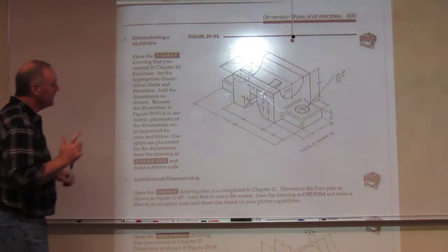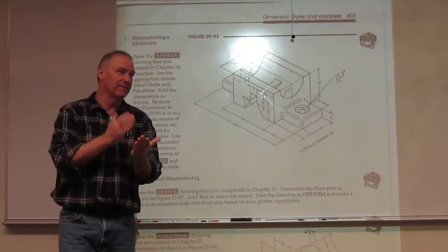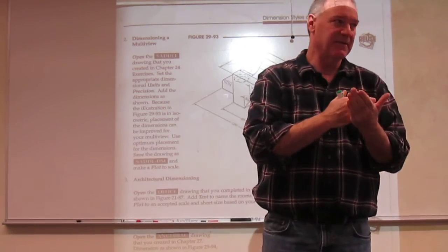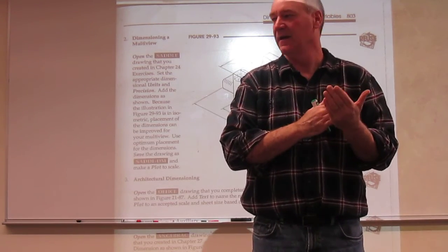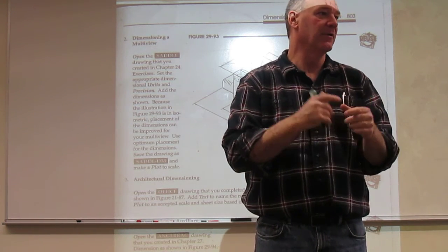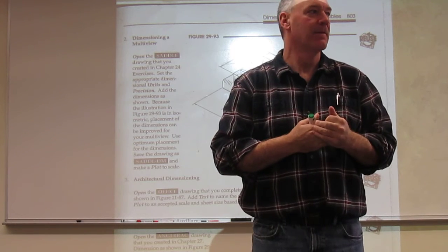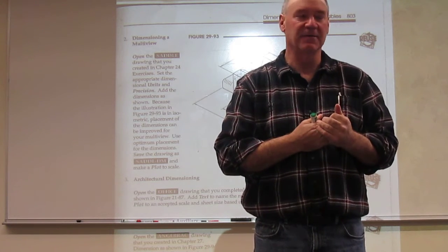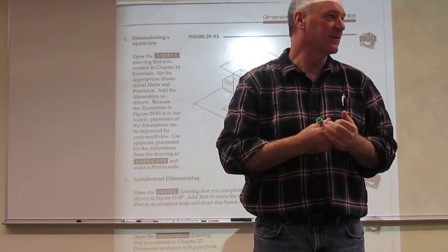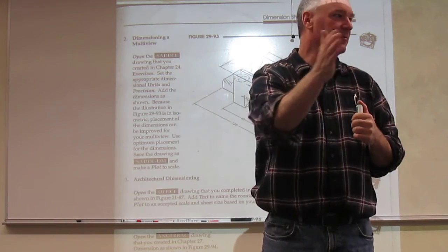When you get these angles, let me just point this out, that are even increments of 15, like 15, 30, 45, 60, 75, 90. Those are ones, in my mind, that many times I will go a point at an angle and not worry about going 2 points. And why is that? It's simple, but also all of your cutting machinery understands that those 15 degrees are worked, and they probably have set points where you rotate to those.